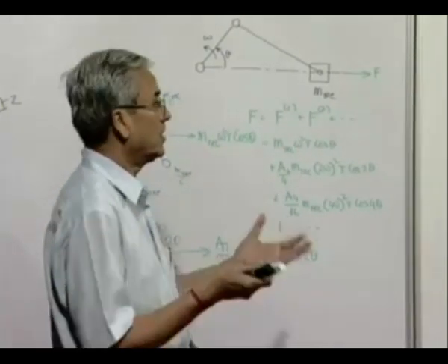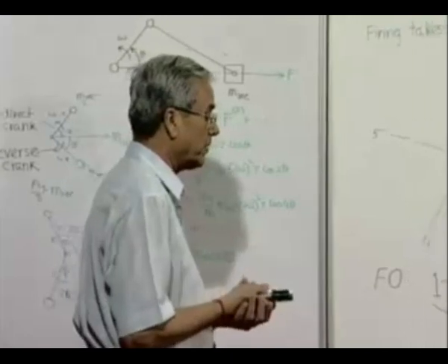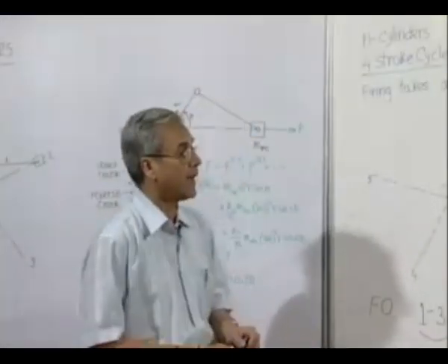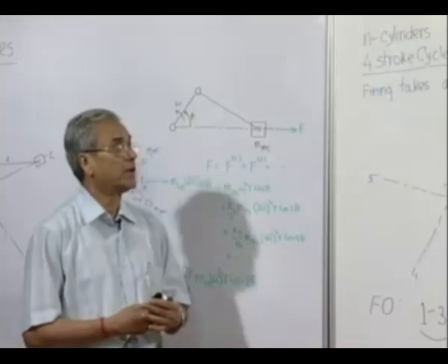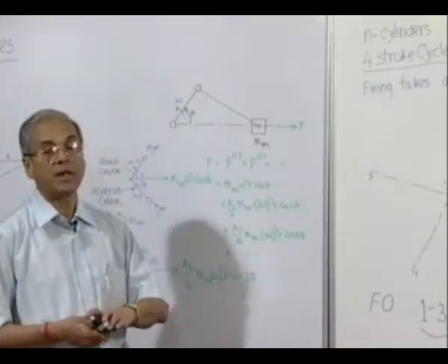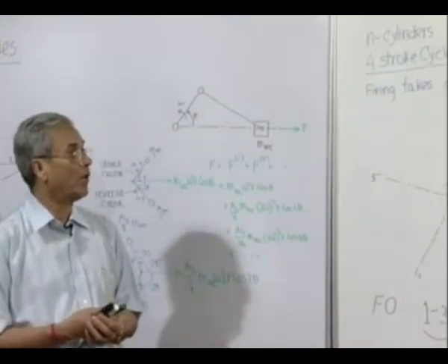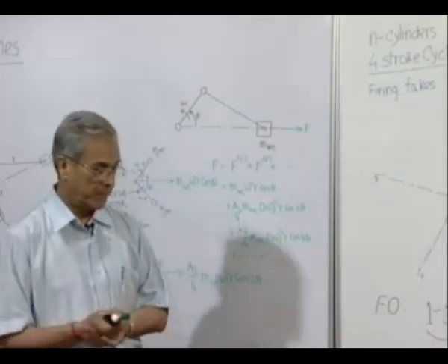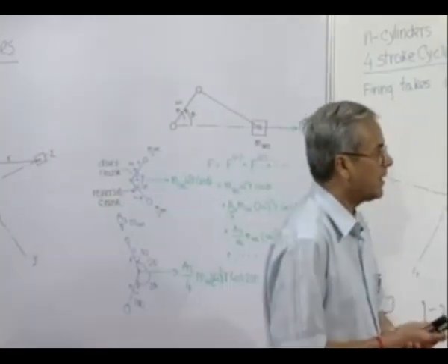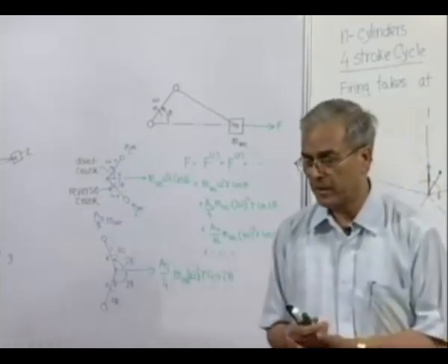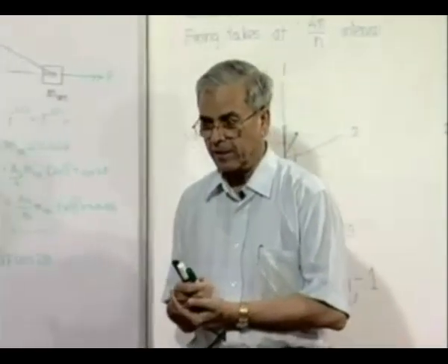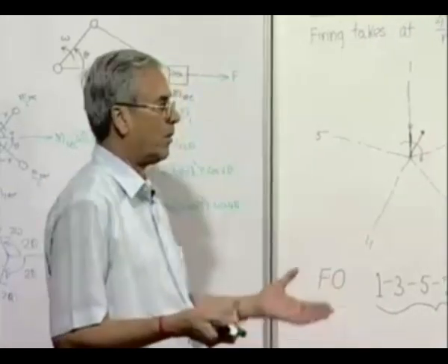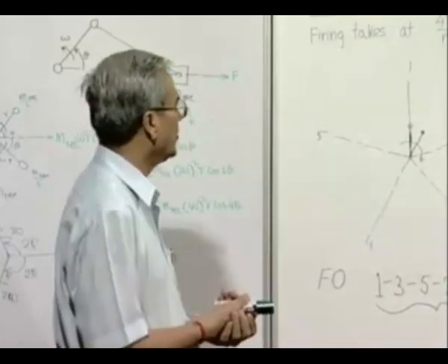So I think this is a situation which we really wanted, that even the higher harmonics are balanced, because aeroplane engines need to be far safer, they should be subjected to lesser vibration, and this kind of more rigorous condition is essential because the speed of operation of these radial engines is generally much higher. So I think we will stop here. We will not go into more complicated situations, like say there are cases where the rotors are flexible or similar things, we will not go into it.